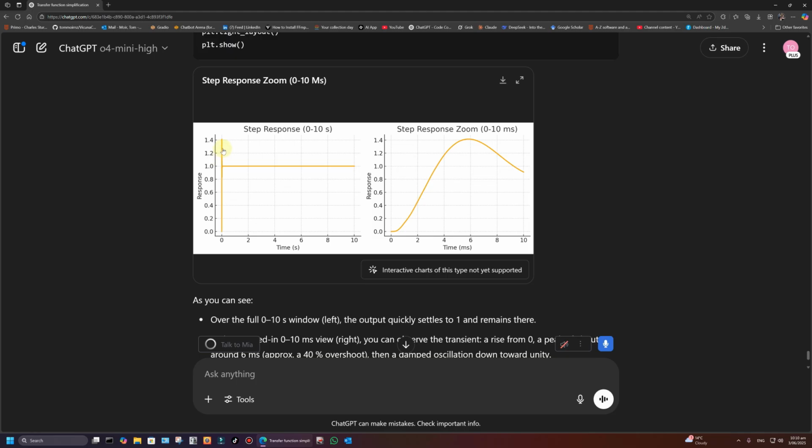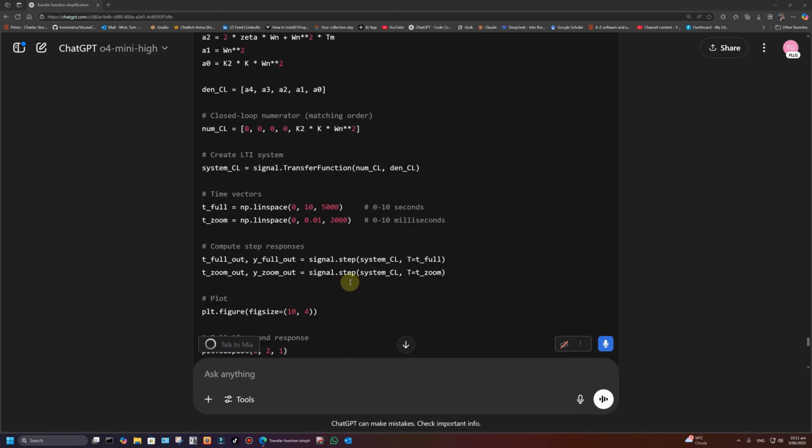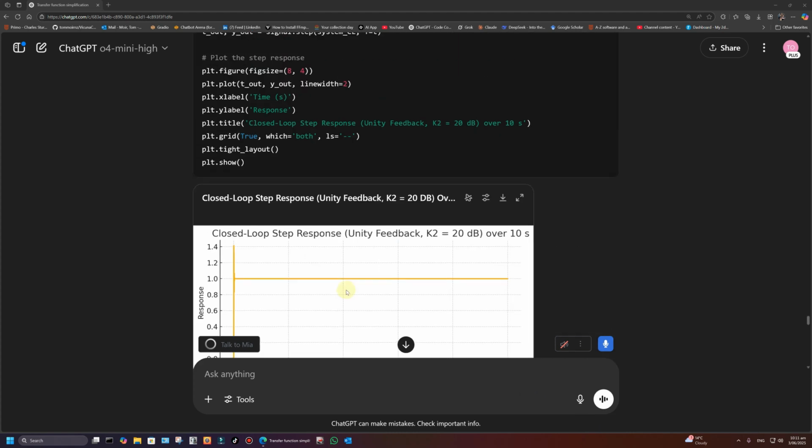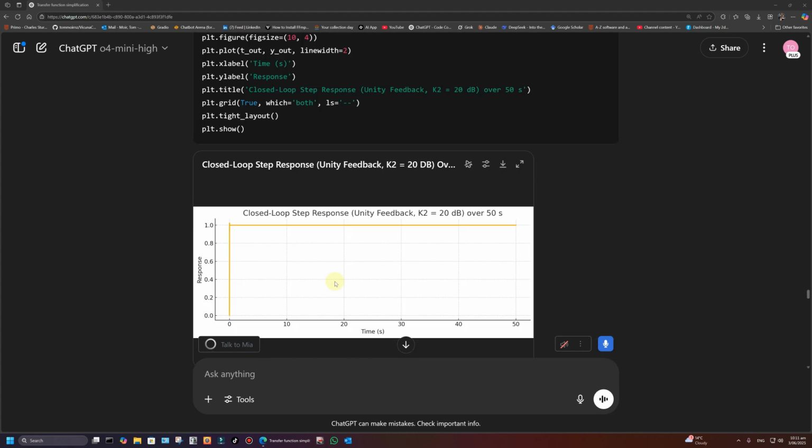I said it would have a 30% overshoot. Well, it's got a 40% overshoot. But anyway, what we're going to do now is design a controller for it to give a half-decent response. Now, in my book, I design using the phase advance, a phase lead. And I actually stick a second integrator in as well.